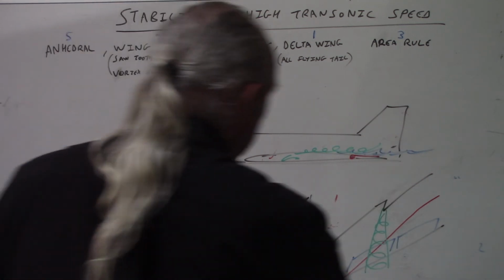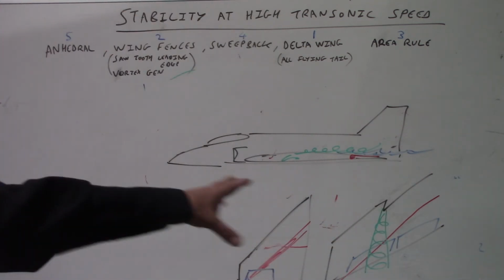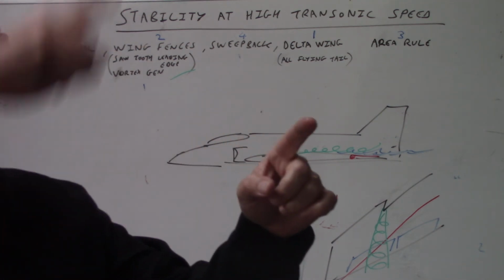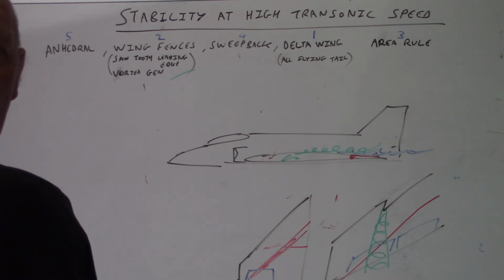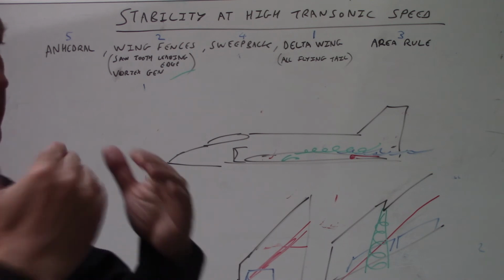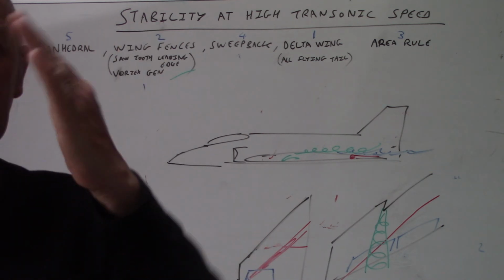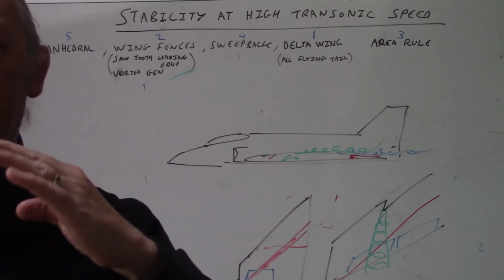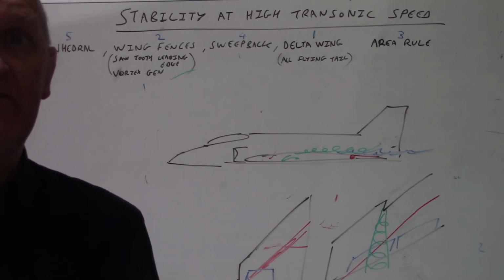Now, if you've got turbulent flow, which is chaotic, and you've got a vortex, which is swirling flow, that swirling flow is controlled. So a vortex will still give you some lift, and if you put control surfaces into a vortex, the part of the vortex hitting the control surface and deflecting off it will still have some control effectiveness.